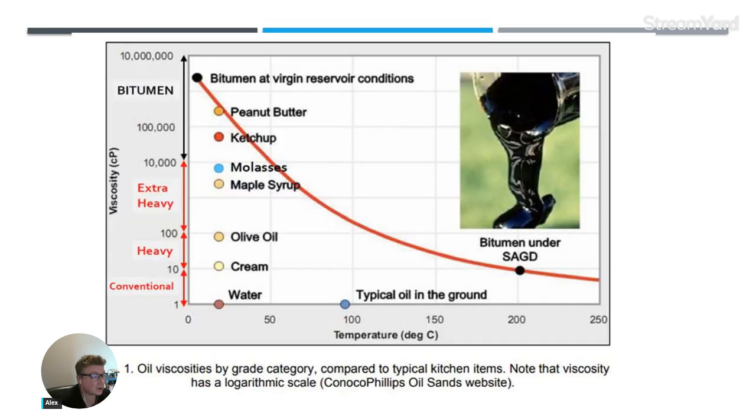by gravity. Now, on relative basis, you can see the curve of viscosity reduction based on temperature, right? So when we get to 150 degrees on that scale, you should be flowing like an olive oil will flow. If you're at 50 degrees, you flow like molasses. If you are at 20, 25, 30 degrees, something like that, it's more like ketchup, but it's almost like no flow, right? Like with ketchup, you almost need to push it, you need to apply some force, and this thing is not just going to naturally flow unless there is some kind of incentive. Or like peanut butter, think about peanut butter, right?